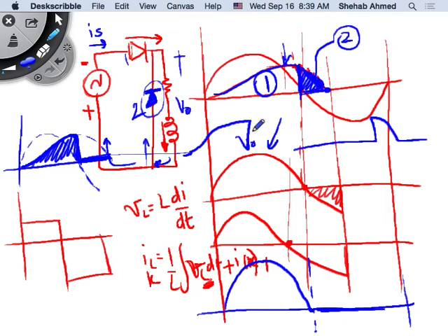And if you were able to calculate beta for that RL case, then you know this point, beta, and you know this point because it's pi, and you integrate the equation for current over the period. The integrations you can do with the calculators, guys. I don't have a problem with that. But at least you need to write the equation that you will integrate, right?